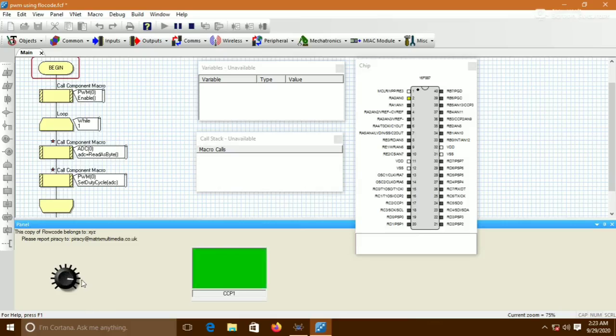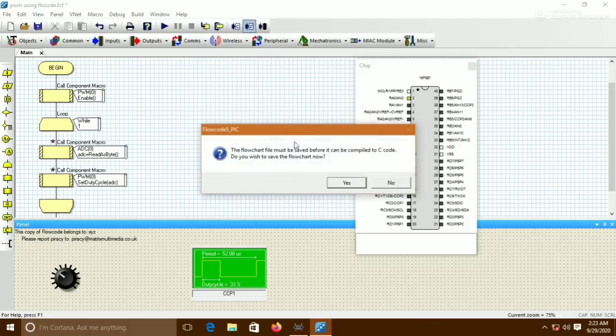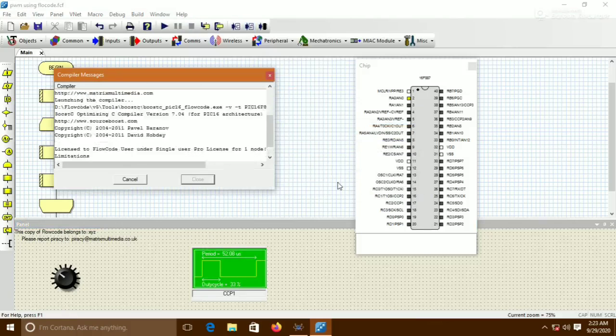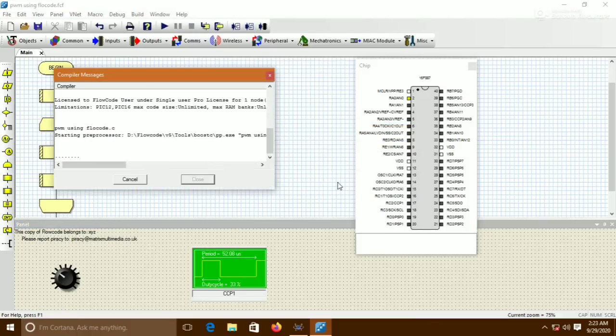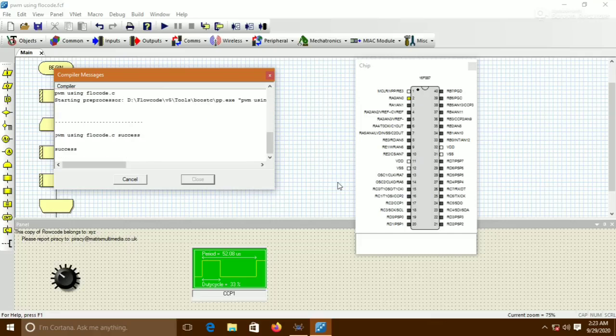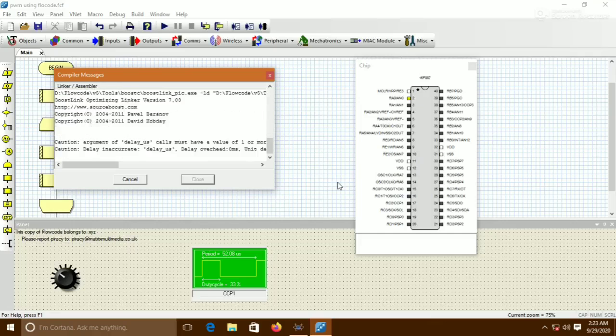Here you can see this. Changing the value of the knob means changing the value of the analog input, so the duty cycle changes, meaning the on time and off time change. Now compile it and after that go to Proteus. In Proteus, first I connect the knob. The knob is connected by default at the AN0 pin, meaning analog 0 input pin.